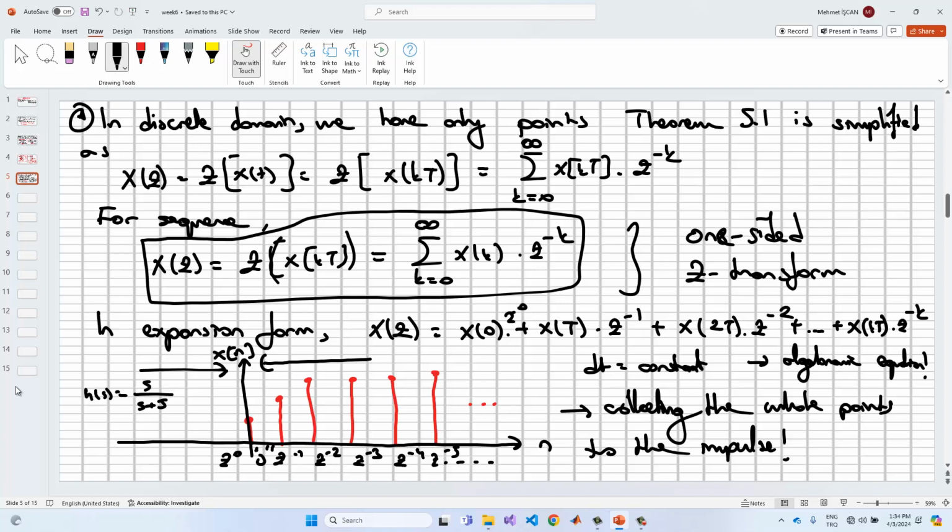But in discrete time, we cannot use s, right? Because we don't have an infinitely small sampling period, right? And so if we have a different dt value, bigger than 0, then we should apply the z transform to represent the transfer function based on the sampling period and the sequence number. This is how we can build the sequence number in here, just like this one.